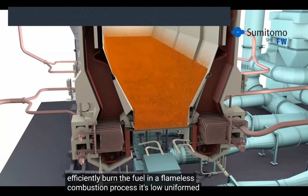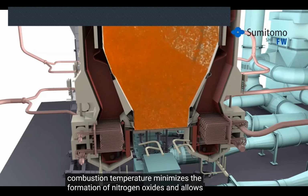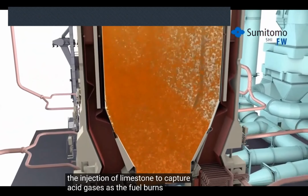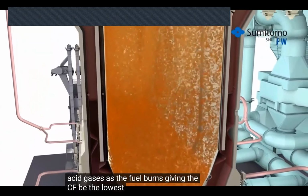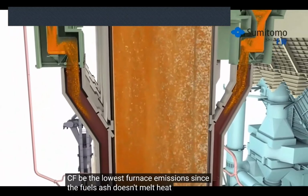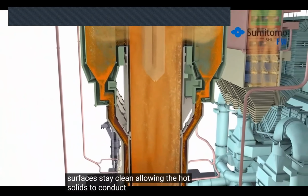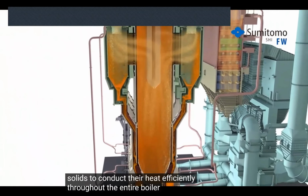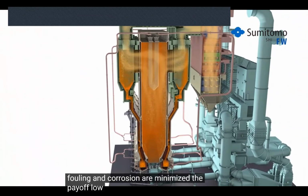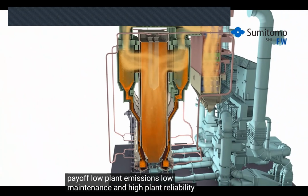Its low uniform combustion temperature minimizes the formation of nitrogen oxides and allows the injection of limestone to capture acid gases as the fuel burns, giving the CFB the lowest furnace emissions. Since the fuel's ash doesn't melt, heat transfer surfaces stay clean, allowing the hot solids to conduct their heat efficiently throughout the entire boiler while fouling and corrosion are minimized. The payoff? Low plant emissions, low maintenance, and high plant reliability.